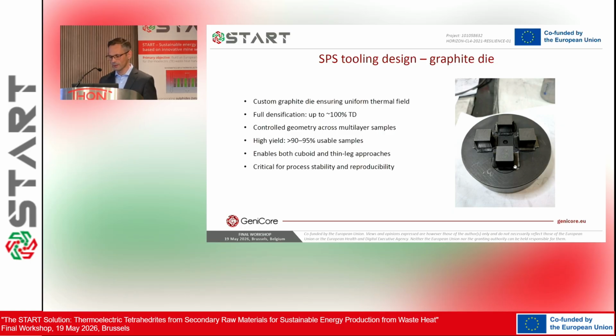To increase the lifetime, some graphite foil can be incorporated to limit the sticking of the powder to the graphite, and conversely to limit the carbon contamination from the graphite die. Other materials for foil can also be used.